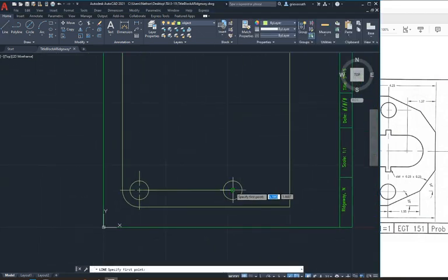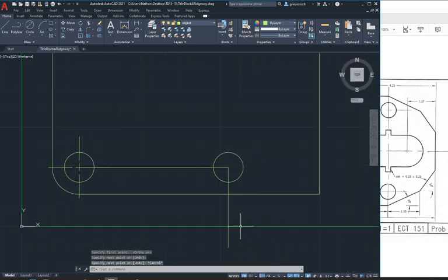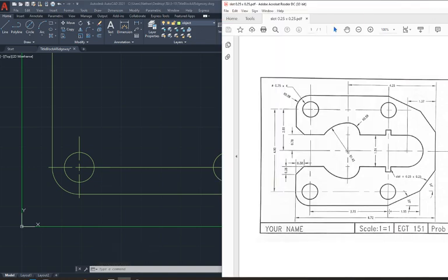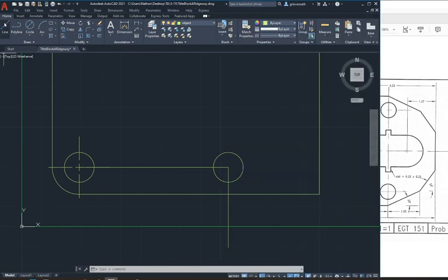Next, I'm going to use the line tool again, turn orthographic back on, and we're just going to go straight down. I know that this crossing point is where this angle starts. I also know that this line is 1.55 and that the angle is 25 degrees. So I'll take another line, turn orthographic off. I'm going to start at this intersection, which is the X. I'm going to drag it out here, 1.55. I'm going to press tab, and now I'm at the angle, 25 degrees. Escape. Just like so, I now have that next line.